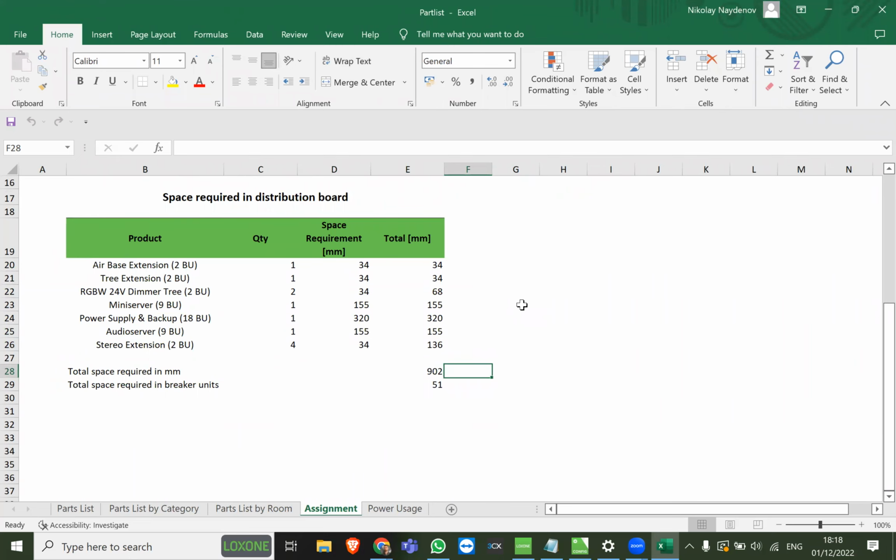So how do I know how big of a panel I would need? Well, this is where we can find it, and we can do a little bit of estimation, or we can think about, hey, I also want to have a few more terminal blocks. I also want to have some space for future-proofing the project. Maybe I'll add another DIN rail in, but we want to overshoot by 1 or maybe half a DIN rail instead of having 5, 6 DIN rails that are just sitting in there, empty space, redundant, and you've paid a lot of money for the panel, and that customer is now thinking, okay, why do I have a panel this big when I only have like 3 rows of devices?